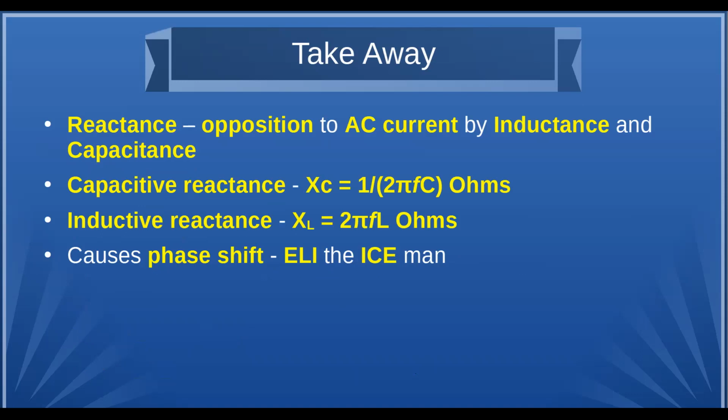There's a good chance there's a math question about those, like the ones I showed, where capacitive reactance is the reciprocal, 1 over 2 pi f times the capacitance. Inductive reactance is just 2 pi f times the inductance. And remember Eli the Iceman, that voltage in the inductor leads the current, current in the capacitor leads the voltage.